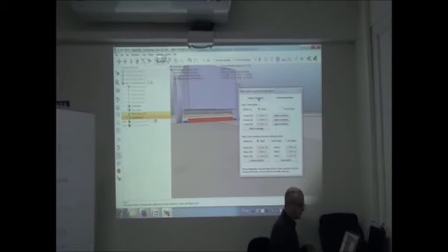if I go to position, position translation, I have a button Apply to Object. What does that mean? When you select an object, it will show these coordinates here. When you select another object, it's another coordinate here. Now, if you do multiple selections, you will have the parameters of the last object. So apply to selection means that all the objects that are selected will get these properties, the things that are here, of the last object selected. So by clicking like this, I'm putting the motor at exactly the same position.